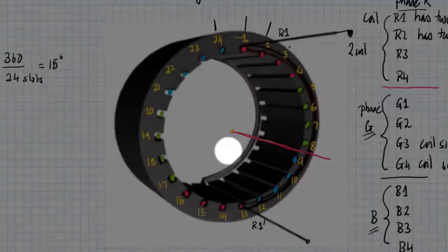Now if you look at where the axes of the other phases are going to lie, suppose we take the B phase, you have 9, 10, 11, 12 here, and it occupies 21, 22, 23, 24. Just like you had the middle of this phase occurring right in between the green and the blue after the red, here again you need to look at the middle being right after this. You have the end of the spread of the B phase, and then you have the next red, and the blue axis would occur exactly here. That is then the midpoint really of the blue phase. So we may draw a line corresponding to that axis roughly here,